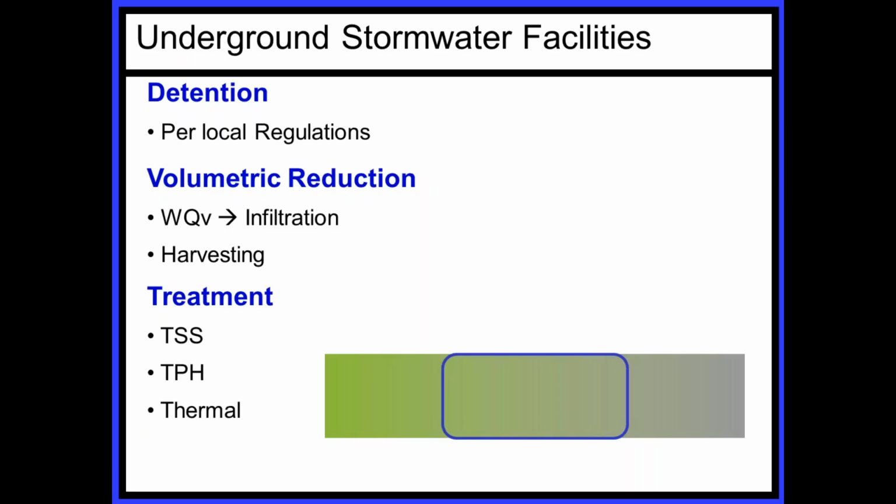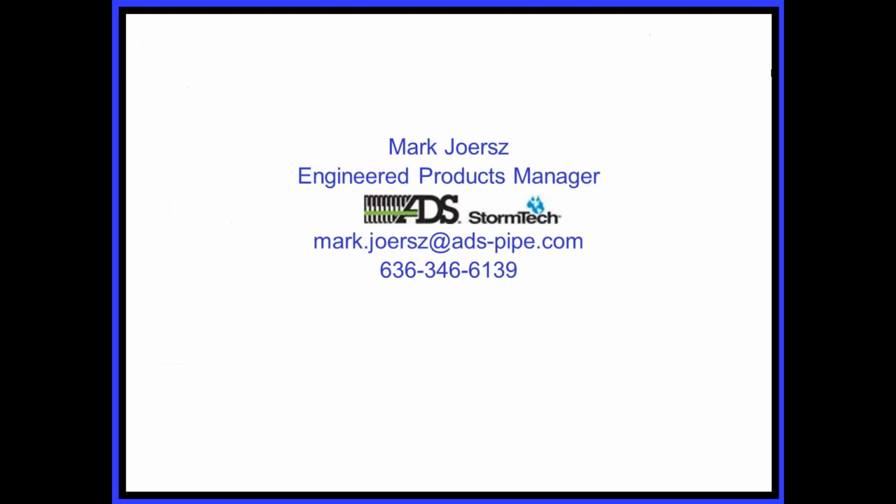And it's really three pieces of that puzzle. You're holding the water, hopefully infiltrating that water, or giving it time to leave the site through the ground rather than through a pipe. And pre-treatment, again, is very important. Without the pre-treatment technique in place, you are going to have a shorter life or a very high maintenance cost, neither of which are palatable.